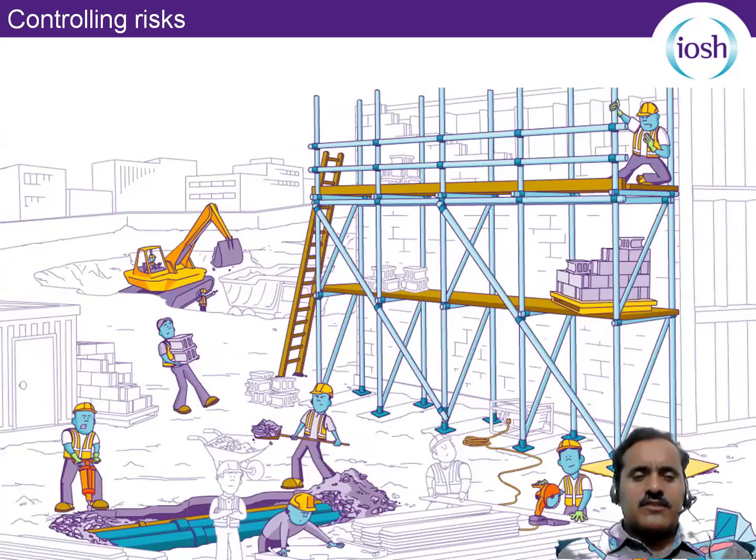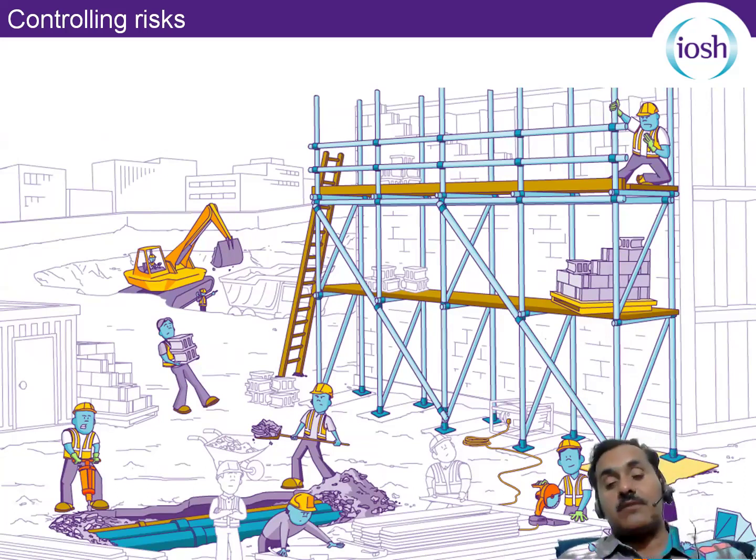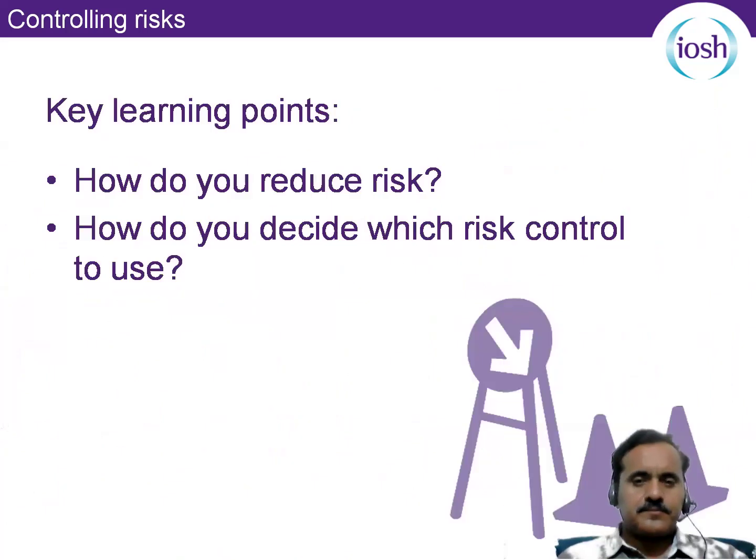And in this picture, you can see there is a crane operation. The area is not properly barricaded. A person is holding some load without safe handling technique. Even there is a drilling machine and some underground utilities like electrical cable, gas pipelines, and some sewerage system there. There is a person on the scaffold, but edge protection is not done. There is a chance of falling. Electrical cables are there, but you can see there is poor housekeeping, and that may lead to a tripping hazard. And there is a cutting machine, but precautionary measures are not properly taken.